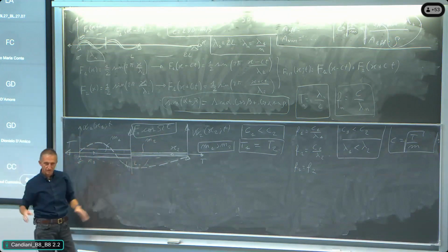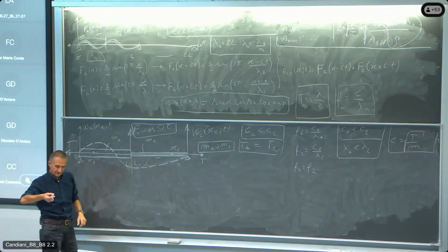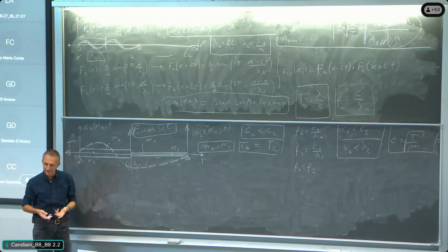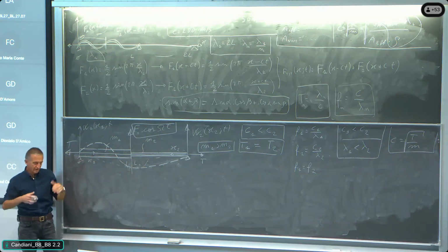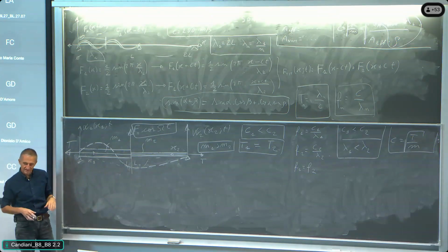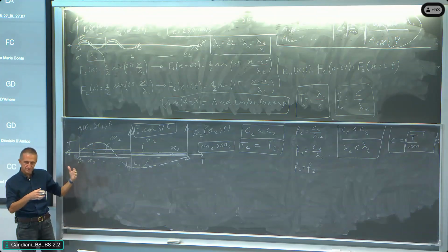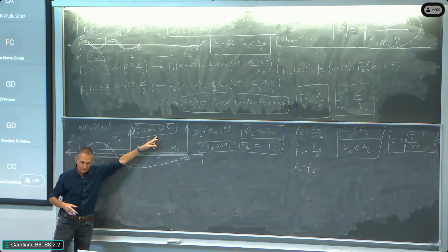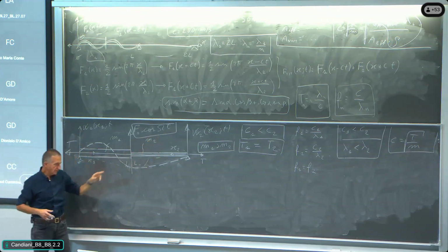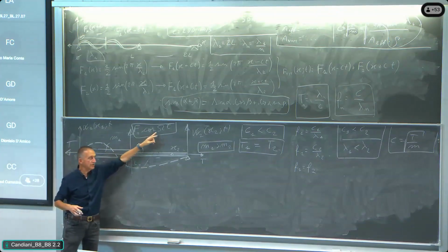The purpose of all of that will be to show that moving the frequency of the excitation, playing with the frequency of the excitation of this force, you will recognize with your code that is running the deformed shape of this object, when we are approaching with the excitation frequency one of the natural frequencies of this system.